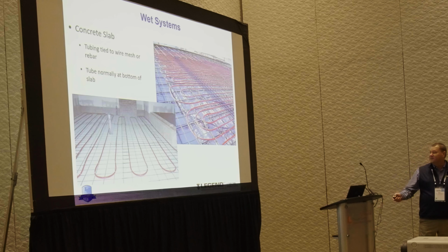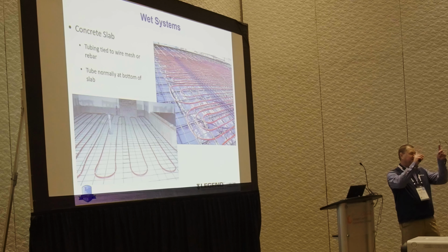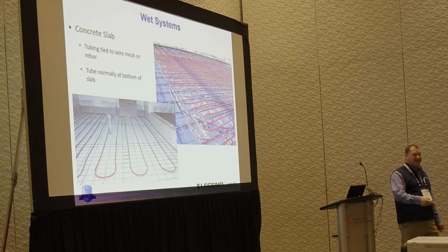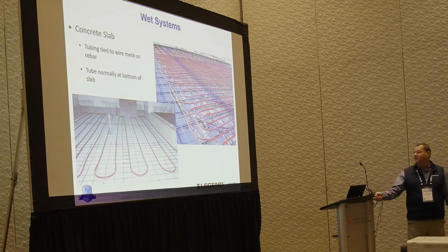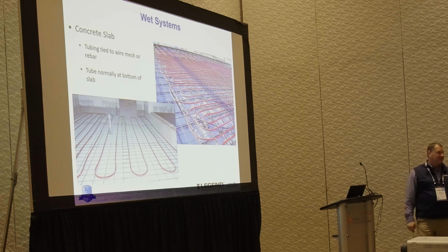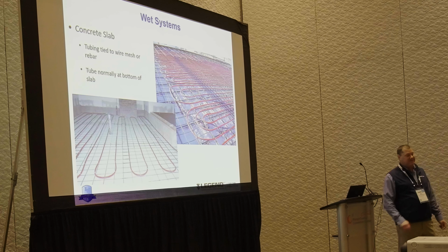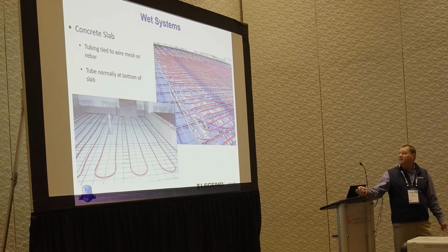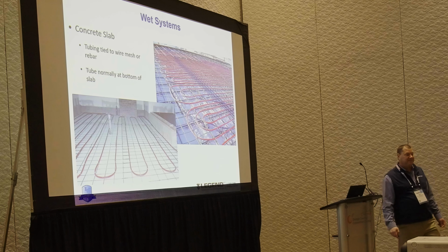Another thing, this is an example, maybe hard to see. Cut those tags. Didn't cut those tags down. If those tags are sticking up through the cement, it's not going to hurt anything. It's really going to look bad. Someone's got to go down and cut them all and grind them down. So not only put them in, but cut them off. If you're using the metal tags, you can push it down, they stay down. But zip ties, you want to make sure you cut them off.